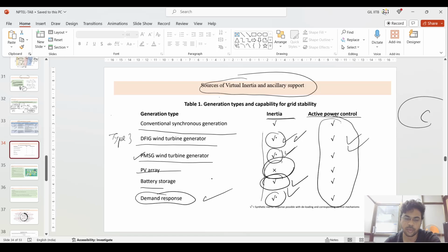Yeah, that can be utilized, but you cannot force the PV array. Though you have a certain DC link capacitor from where it is being connected, and you have some MPPT algorithm working for the DC boost converter kind of thing, you cannot force the PV array to generate that power. But when the ability is there, you can utilize that.